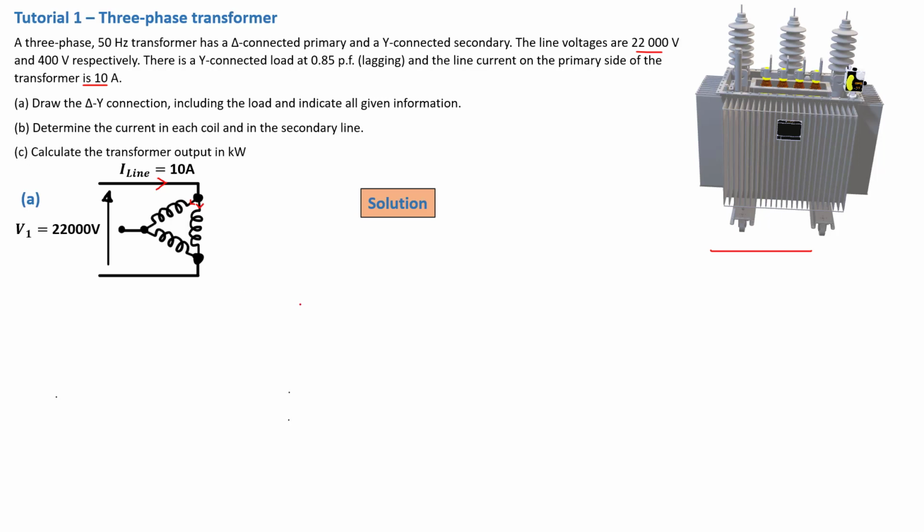Now the reason is very simple. First of all, it's because of the cost, because remember, in delta we are only going to have 3 wires, okay, only 3 wires are going to be used for transmission, so it reduces the cost. And also the delta winding will allow a third harmonic current to circulate within the transformer in a closed loop, and this will prevent the third harmonic current from flowing into the transmission line if there were actually a fourth wire that is linked to the earth.